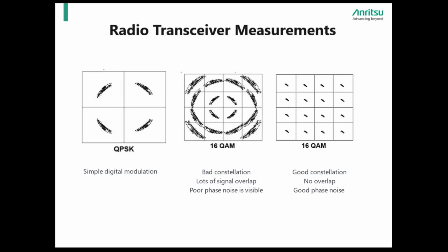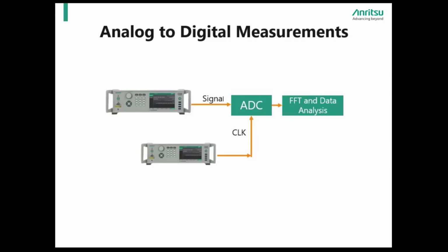Please note that this is the simplest case and that digital modulation schemes are far more complex, with systems supporting 1024 QAM and higher. The final example that illustrates why phase noise is important in measurements will be the effective number of bits measurement. When we talk about ADC measurements, we care about signal-to-noise ratio, or SNR, spurious free dynamic range, and effective number of bits.